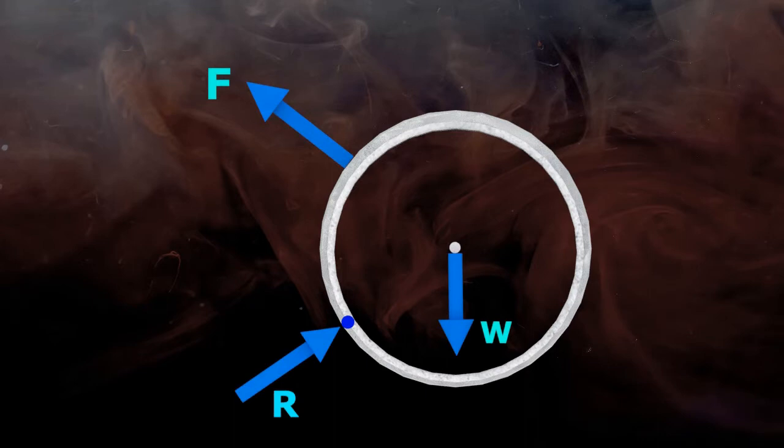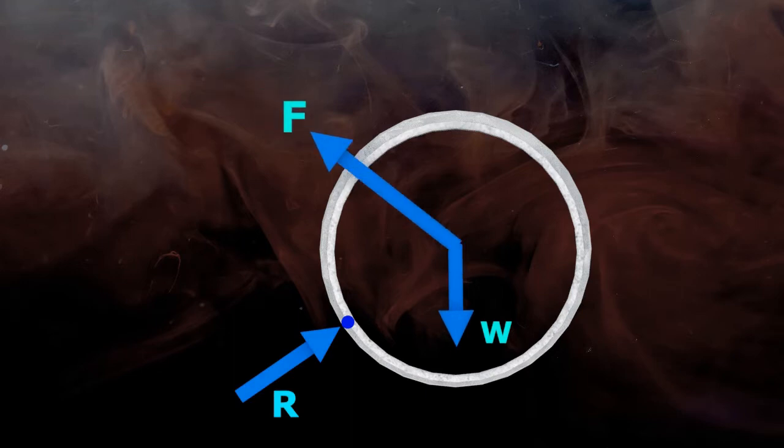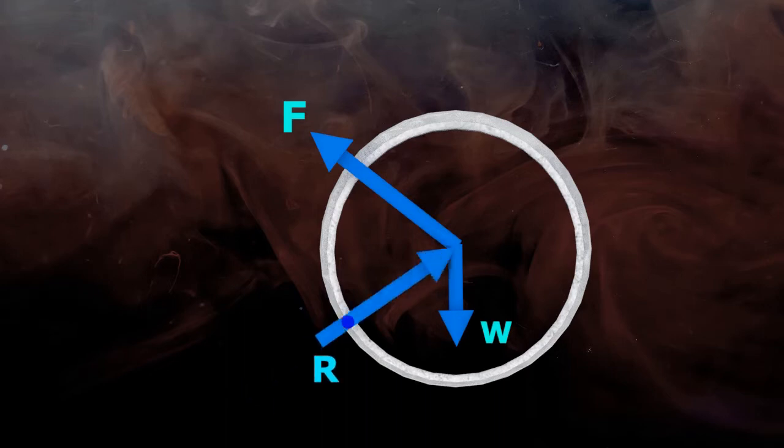Here one important concept should be cleared. It is mentioned in the problem statement that the pipe is just lifted over the curb and it is not actually moving. So it is in state of equilibrium. As force F and self-weight W meet at center of gravity of pipe if extended, to hold the pipe in position and maintain equilibrium, reaction R must pass through the same point too. But why it has to pass through the same point? Let's understand.